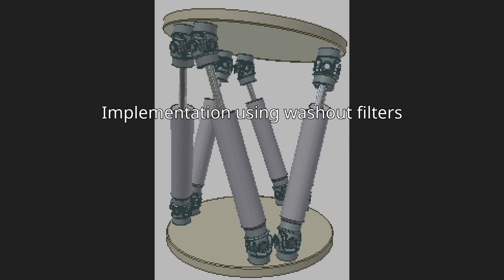Implementation using washout filters. Washout filters are an important aspect of the implementation of motion platforms, as they allow motion systems, with their limited range of motion, to simulate the range of vehicle dynamics being simulated. Since the human vestibular system automatically recenters itself during steady motions, washout filters are used to suppress unnecessary low-frequency signals while returning the simulator back to a neutral position at accelerations below the threshold of human perception.